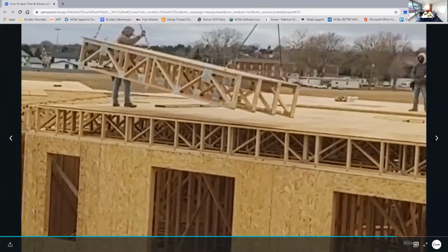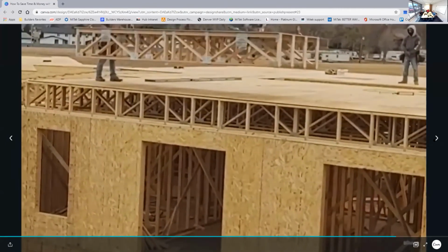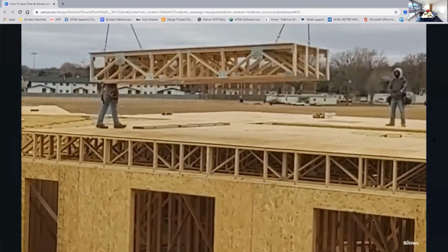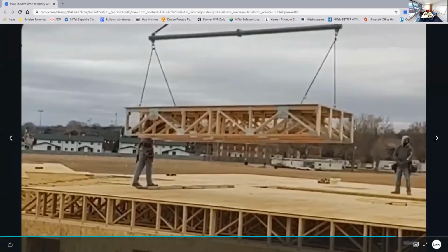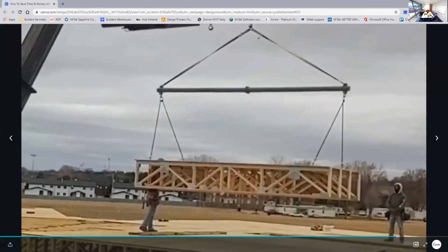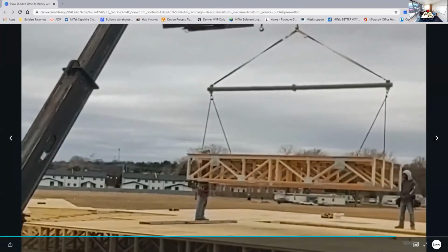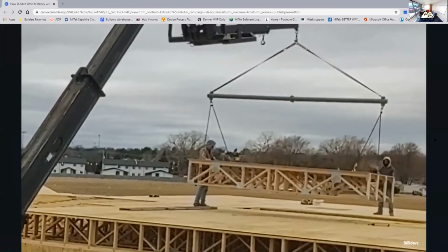The anchors they use on those. What's that? Mention the anchors they use, how slick the anchors work. Yes, we have a quick anchor system where once they get that panel set, it's just like a toggle, and it will release the anchor in order to lift. And that's been a very great application and very well received by the framer. Kind of functions like a rock climbing carabiner where you squeeze the trigger on it and it releases, and then you go to your next wall.